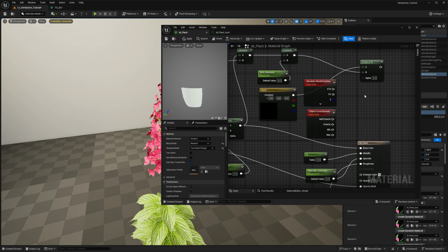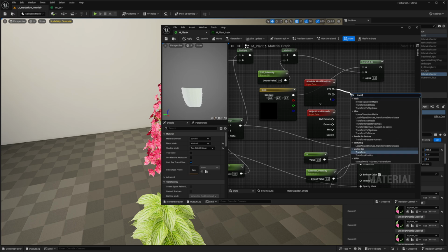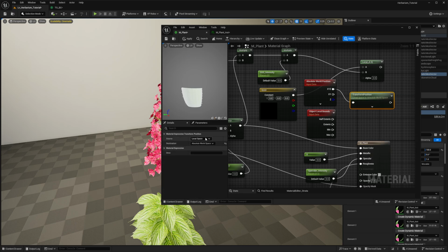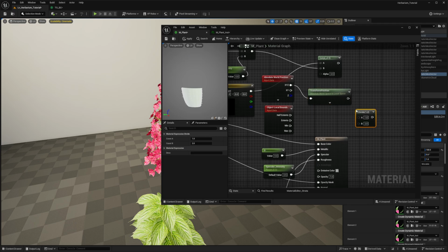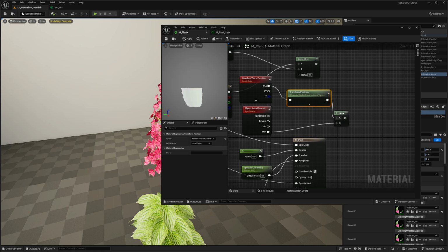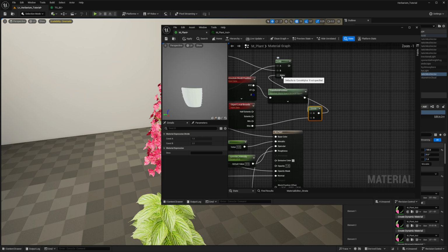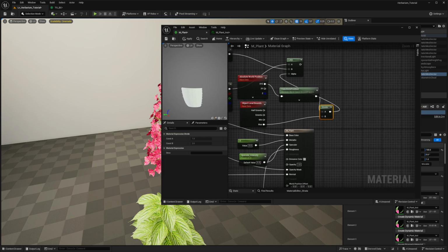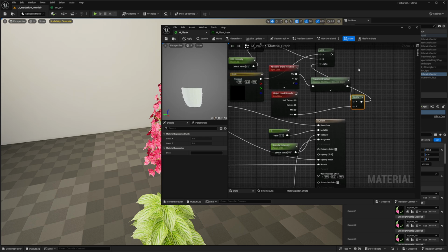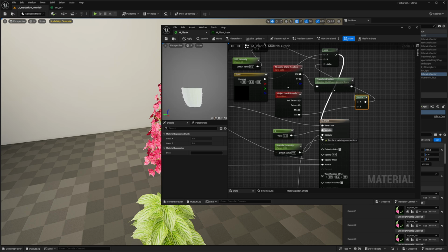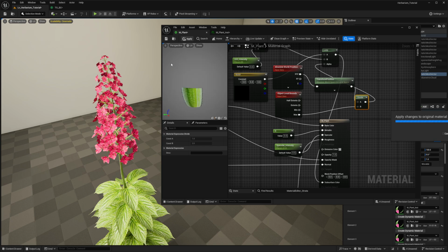So what I want to do is transform this position from absolute world space to local space. I'm going to then divide the transformed local position by the max object local bounds, and I'm going to plug that into the alpha like that. And then this lerp that we've got in here can actually go into our subsurface color in there, right? And now we're going to press apply.